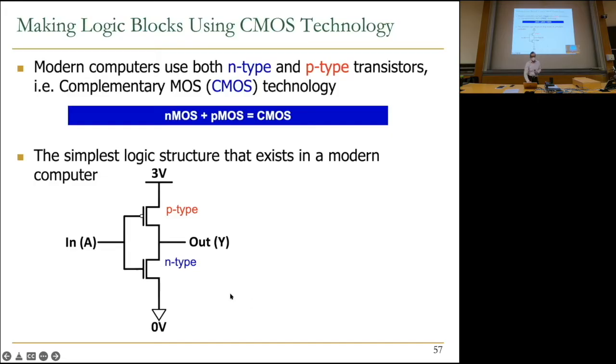So if I ask you, what does the circuit do? What would your answer be? I have one. It's a NOT gate. Does anybody know what a NOT gate is? Yes, in the back. Exactly. It's an inverter, basically. It's the gate that inverts the input. What does this mean? If the input value is 0, you get a high voltage at the end. If the input value is high voltage, you get low voltage or 0 voltage at the end. Let's take a look at how that works.